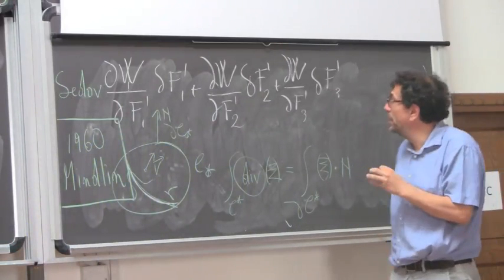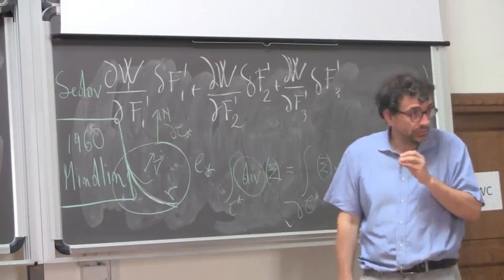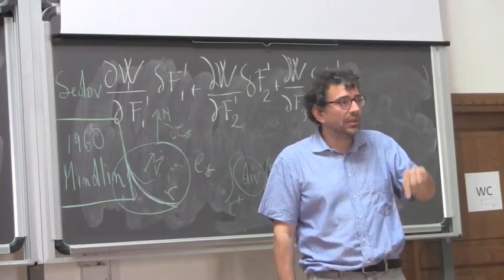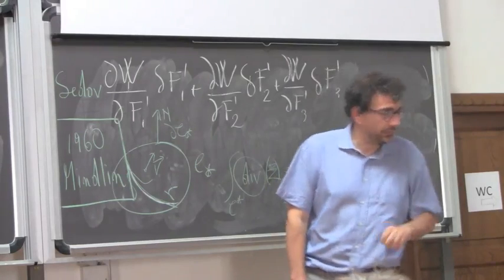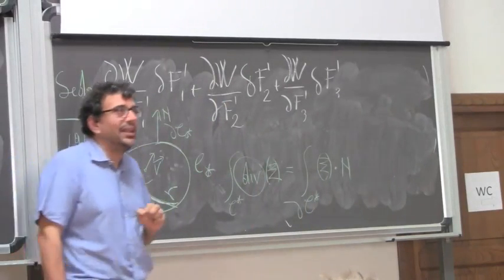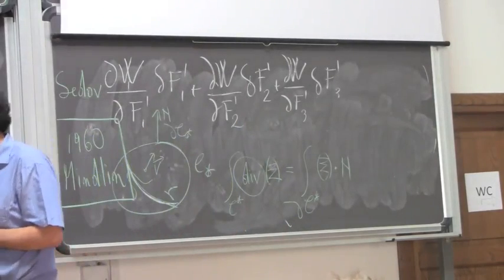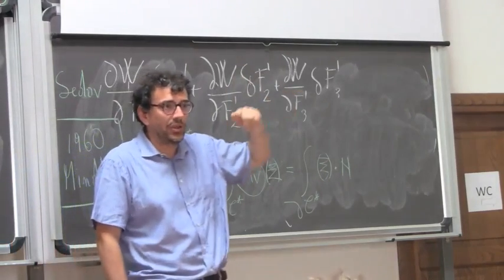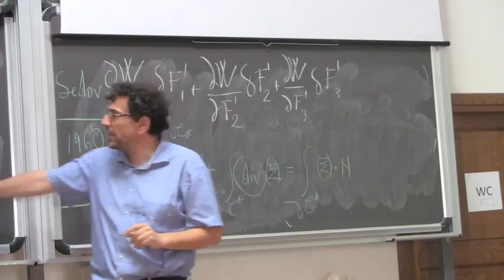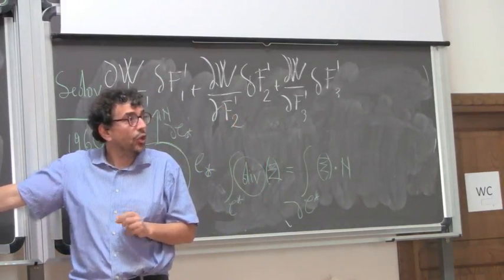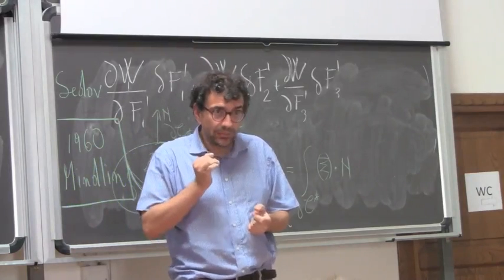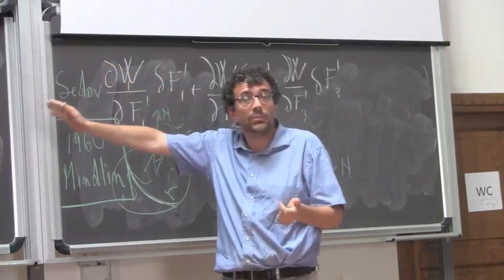Okay, so what they are teaching you is a bad résumé of the final results obtained in terms of variational principles. I try to explain to you how. They wake up one morning and they say that there is a tensor. It is not a pure tensor. They consider the Cauchy tensor in the Eulerian configuration. And this magic tensor is used for expressing forces per unit area. So what they do, in order to avoid integration by parts, so in order to avoid the calculations, we needed less than 1 hour.